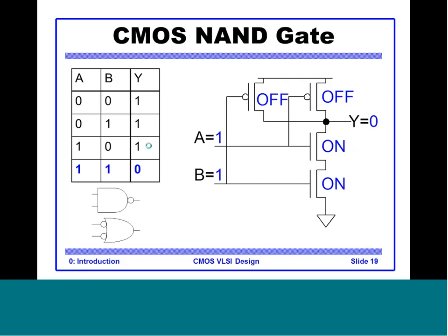So what we see here is that when the gate type is NAND, the pull down represents the complementary functionality of a NAND gate. The complement of a NAND gate is nothing but an AND gate. So the pull down circuit is a series connection, since series means AND, of the complement of the gate we want to achieve. We will look at this concept in detail later.